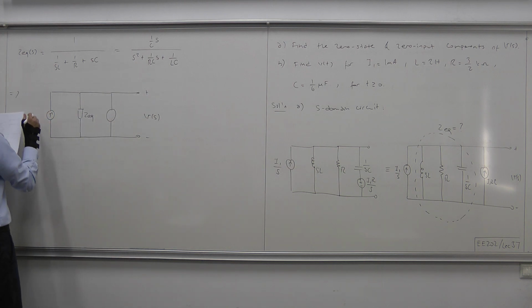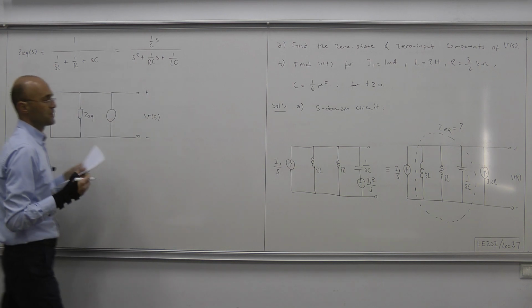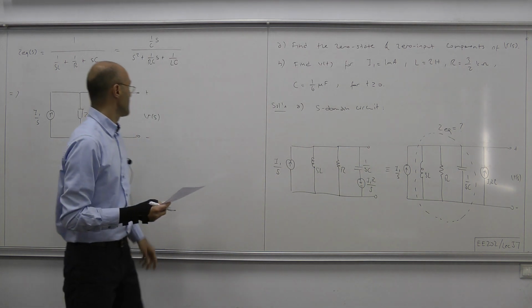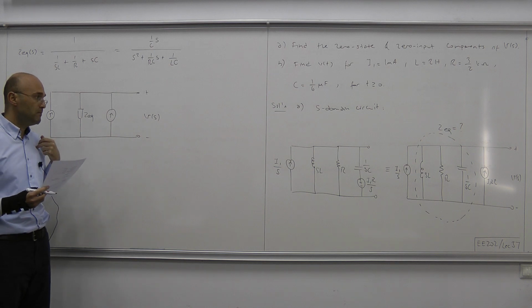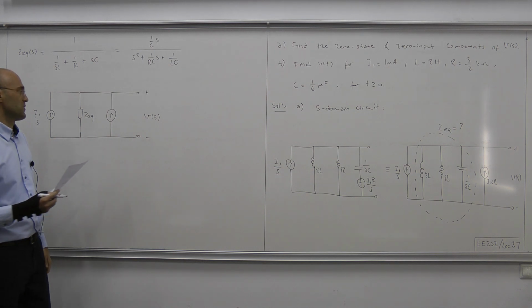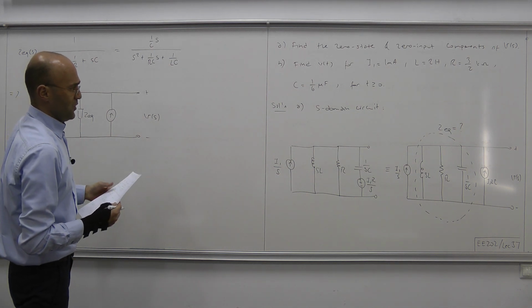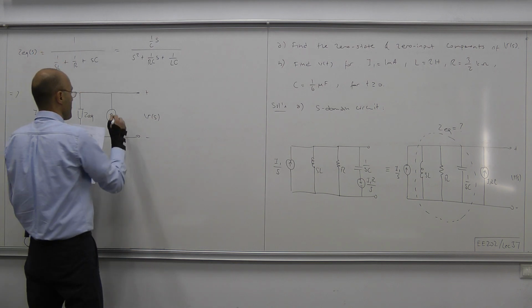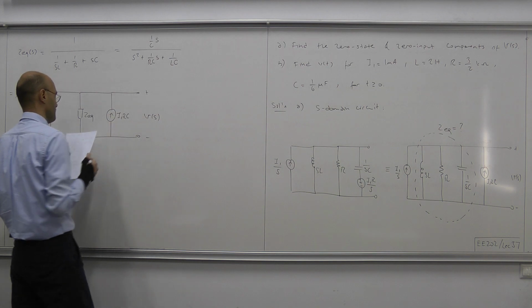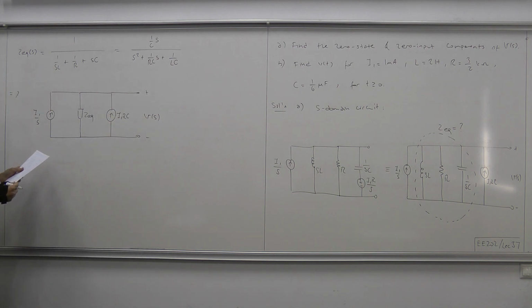This is I1 over S, okay? This source, and this is the source that represents the initial condition of the capacitor, okay? Which is CV0, V0 being I1 times R, we have I1 RC. I1 RC, okay? So, okay, let's make it clear. This represents the external inputs.